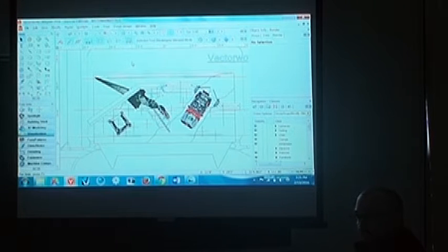If you didn't really pay any attention to it and you need to go back in and organize it now, using that select similar tool to select similar things, you can then apply them to the classes and layers that you want and kind of organize your drawing. That's a fast way to select like objects.